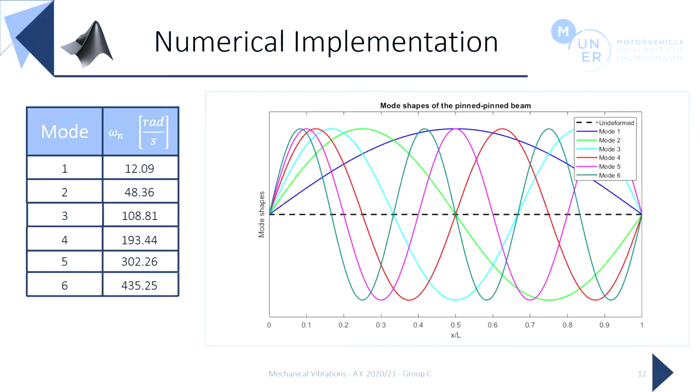Of course, increasing the natural frequency, we can clearly see how the number of nodes increases as well as the number of peaks. For us, it's worthy to remark that the amplitude shown here in the graph is not representative of the real structure, instead it's just arbitrary. Furthermore, it is good to stress that taking as a reference the first 6 modes of vibration over the possible infinite brings an incredibly small error, as in real structures, the very high frequency modes are unlikely to occur for the intrinsic characteristic of the system itself.